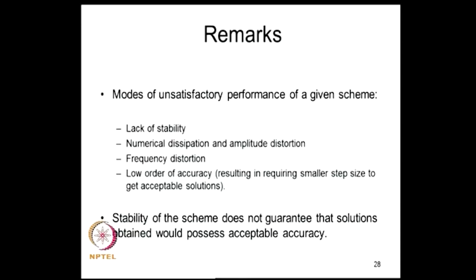So this is how the backward and forward difference schemes perform with respect to a single degree of freedom system. But our objective is really to apply these methods to multi-degree forced oscillation problems. Now we can make a few remarks.